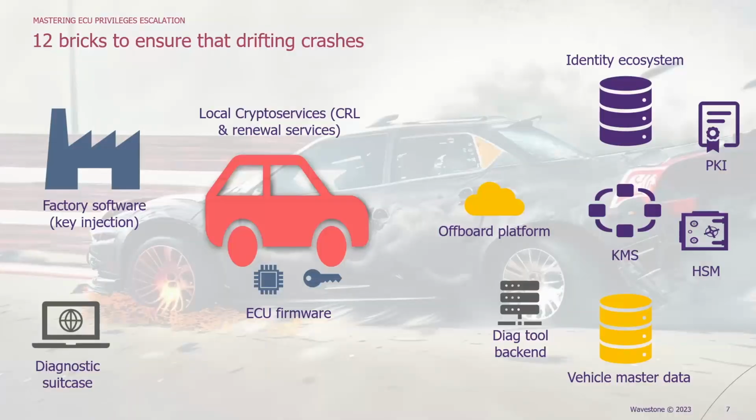So I'm not managing any password locally. I'm not managing anything. The diagnostic suitcase is implementing the security, and in the end, no one that is not a trusted car dealership with a trusted diagnostic suitcase can do anything on my cars. So you can imagine exactly the same thing with a PLC. You have an engineering tool for your PLC that could rely on certificates that are actually issued by an infrastructure that is your own.